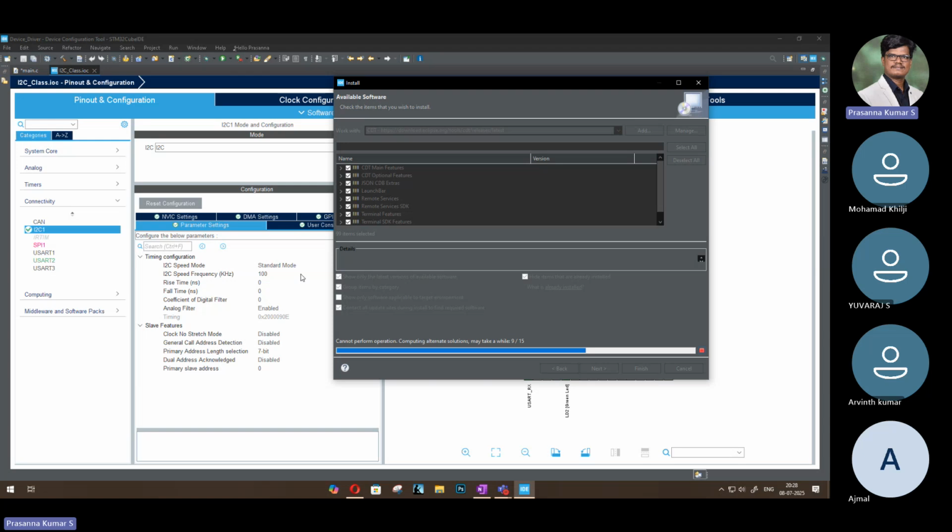The thing is, once you write the program or download the program to that particular microcontroller, it will be running. It just requires a 5 volt supply through this USB in order to turn on. So connect the board which you are going to see the output of to your PC, and then click debug and open it. So your debug monitor will be open for that particular board, whichever board you are going to see the output.